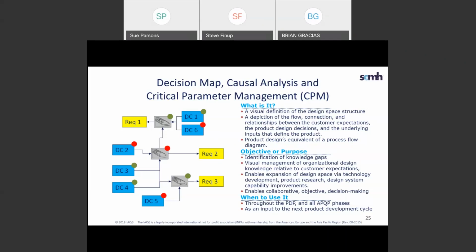The gray boxes depict relationships between inputs and outputs, where transfer functions should be identified and also are coded for whether you know or don't know the knowledge contained therein. The blue and gray boxes and their knowledge status provide failure modes and causes to the DFMEA. And finally, they create and visualize knowledge of the product design space. And here, we want to bring in everything we know from physics, from tests, simulations, rules of thumb, experience, customer experience, field experience, and so on.